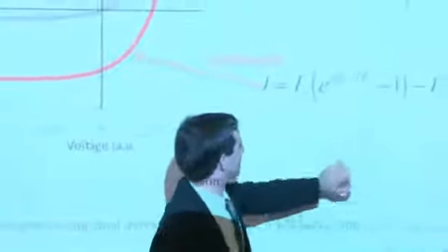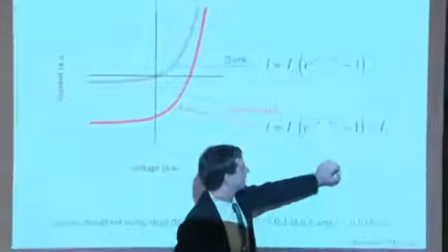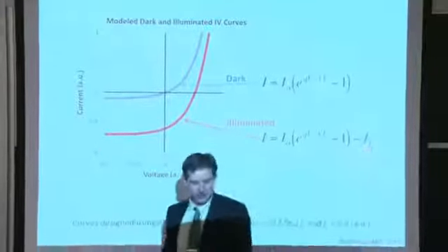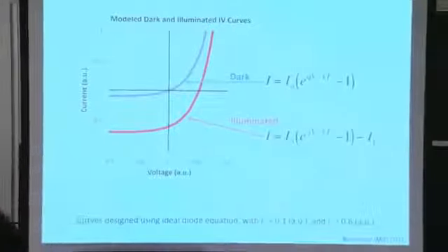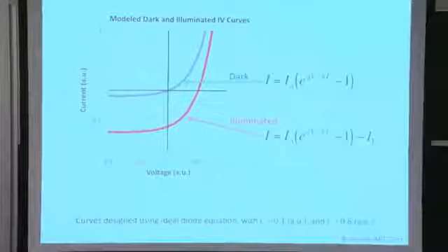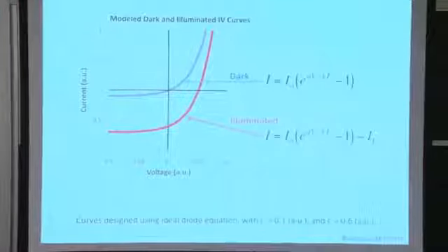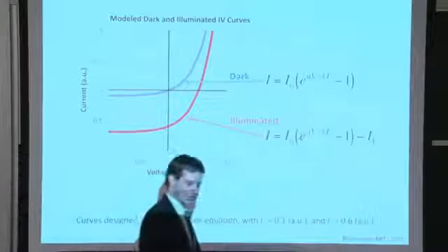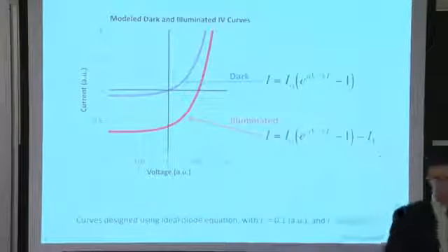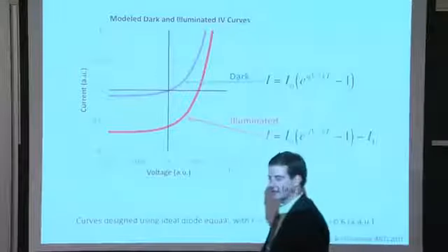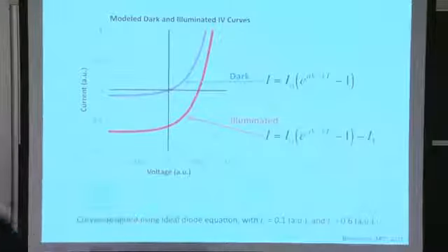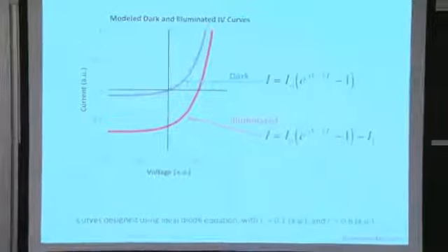Wake up, folks. The I sub L, just to really recap here, we have this ideal diode equation, the illumination current coming in from our light source. And in our little setup, how many batteries did you see there? Look closer. How many batteries do you see total in our setup? Look especially at that light source coming. 2 of them, right? There's a 9 volt and a 1.5 volt. All right, so one of them is powering the light source. And we have as well bias to the solar cell device, right?